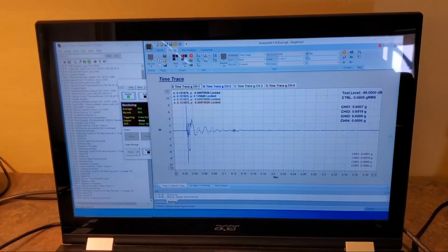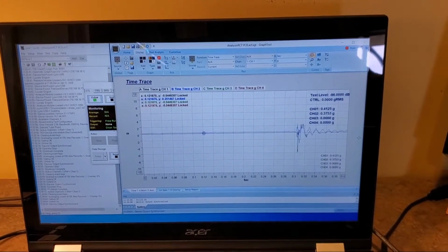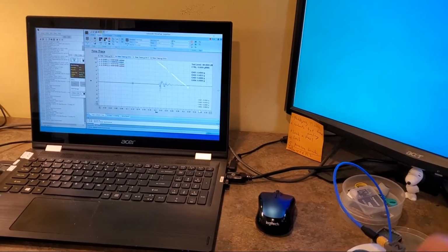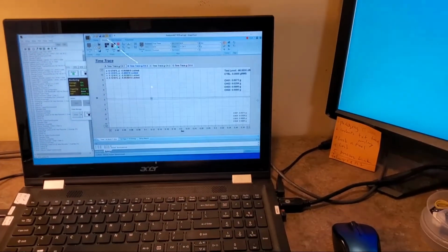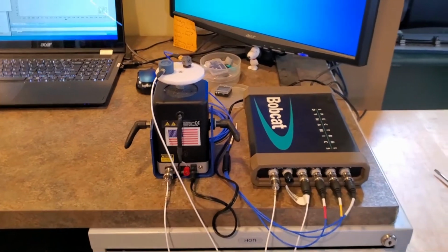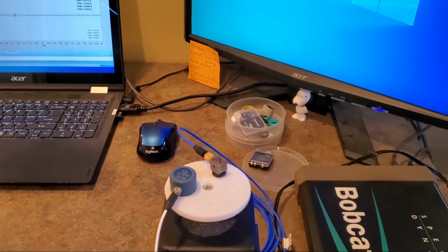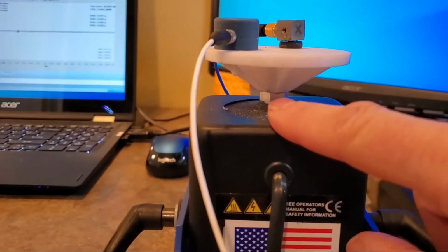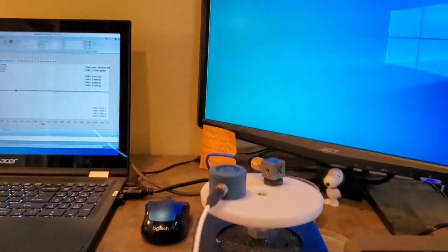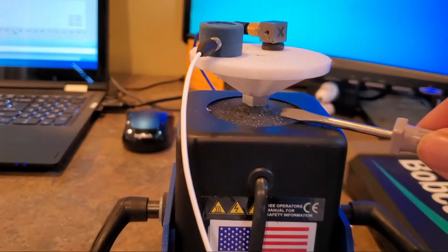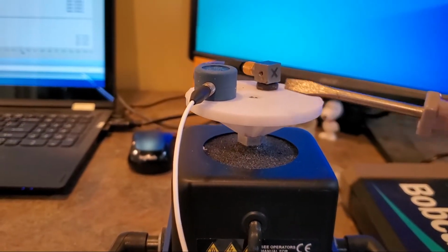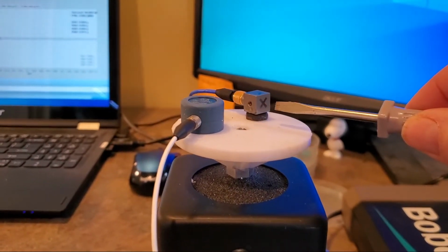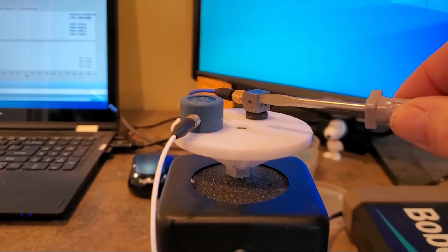So there's some motion on the 2 accelerometers there when I tap. When I tap the top of the shaker, you can see the feedback on the accelerometers. Okay, we have fully cabled up now. We have 2 accelerometers on top of the shaker, head expander, which is in white. So you can see the shaker head is that small silver screw in there. So that guy in there is the top of the shaker. The white piece is the head expander. Accelerometer, single axis accelerometer, triaxial, XYZ accelerometer there, measuring 3 axes.